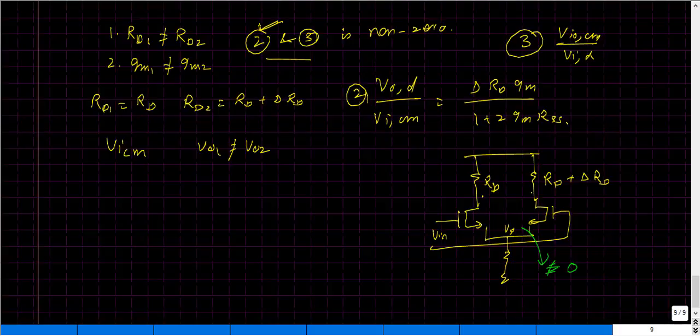Just look from the input perspective. From the input, the signal is measured with reference to the ground, and with reference to that, this entire bottom part of the circuit is basically a symmetrical circuit. It becomes asymmetric when we observe the outputs, but otherwise with respect to the input the circuit is still symmetric, and due to which, under this condition, I can still assume that this node is equal to 0.